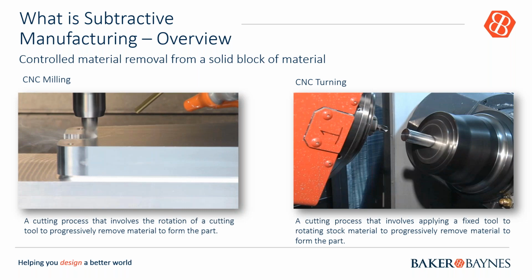If you look at the fourth axis tool orientation itself, we find that the workpiece moves up in the orientation of the axis that it needs to move, and the tool comes in, does its machining, and it moves in its 3 axes, as you can see in there. With fourth axis simultaneous, you see that the workpiece and the tool will actually move simultaneously.